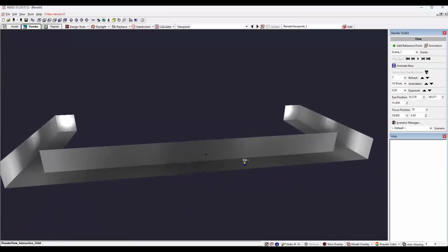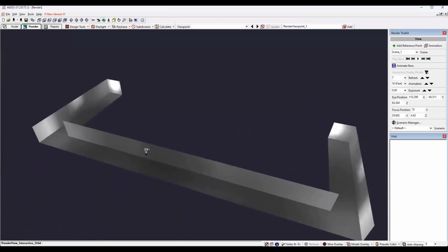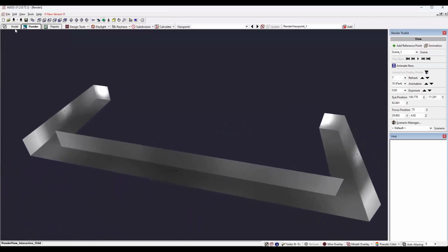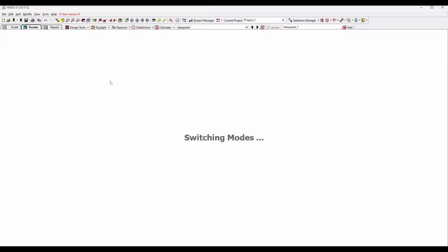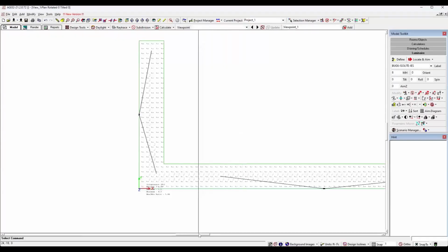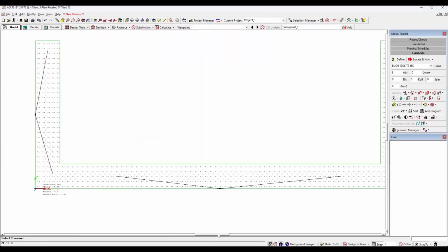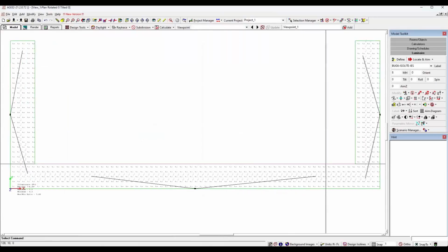So we can see that when we translated these things up, it's really important to set your mounting height first, because when we translated these things up, it looks like the aiming points ended up moving along with them. So this is going to be an important lesson to teach us one more functionality in our step 5, which is adjusting to meet code, which is re-aim luminaires.